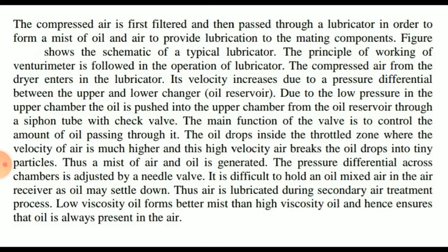The main function of the valve is to control the amount of oil passing through it. The oil drops inside the throttled zone where the velocity of air is much higher, and this high velocity air breaks the oil drops into tiny particles. Thus, a mist of air and oil is generated. The pressure differential across the chambers is adjusted by a needle valve.